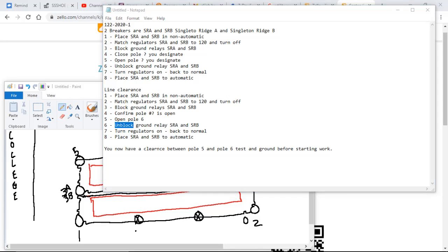If another guy is down there and the dispatcher has just given him an instruction to do something, you cannot proceed to your step until he is done. You cannot go from 1 to 3 or from 4 to 7. It's got to go in step order. Well, I was asking, have you been in a situation where you requested a switching order and somebody's like, hey, I'm actually between y'all, and you didn't know they were there? No, no. The circuit's got to be completely clear before you can proceed with switching. That is really scheduled out by your dispatchers. Usually the dispatchers have scheduled that out.